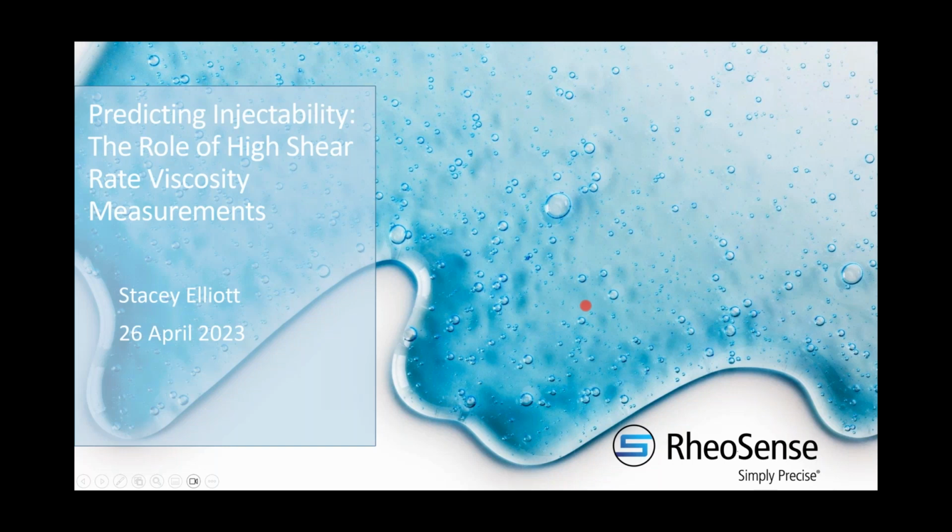And it's going to be dependent on whether that fluid is Newtonian or non-Newtonian. So Newtonian is shear rate independent. Non-Newtonian means that our viscosity will vary as a function of shear rate. The most common form of non-Newtonian behavior being shear thinning. And that's actually the examples we have today that will have shear thinning data.